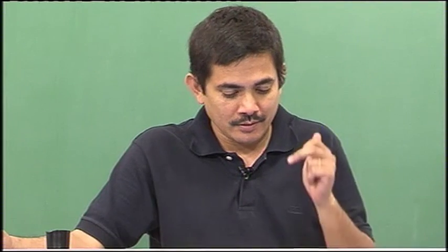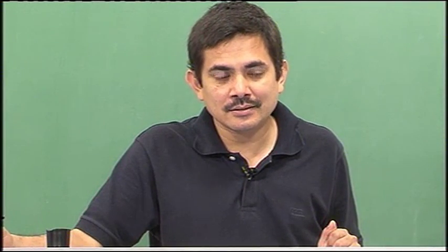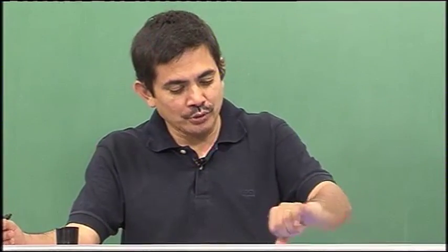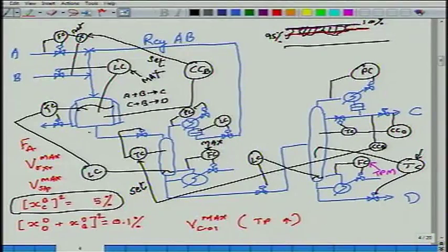Okay, so level in the stripper starts to go down. The level controller increases the temperature set point inside the reactor. Because the temperature set point has increased, more consumption of reactants happens, therefore more C and D are produced in the reactor. Therefore the feed to the stripper, which is the reactor effluent, will be richer in the heavier components, C and D.